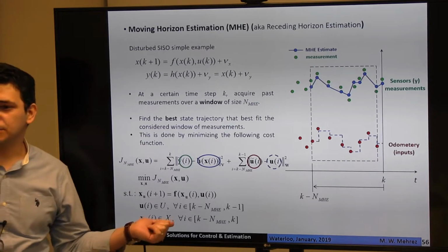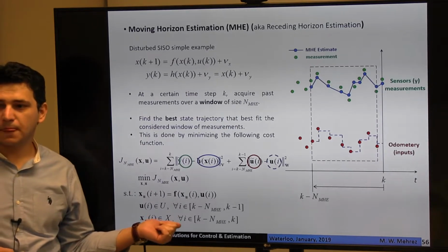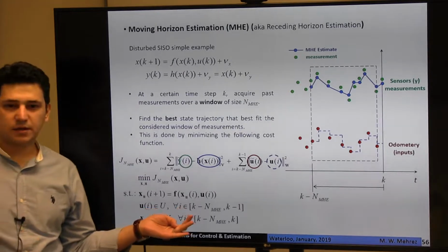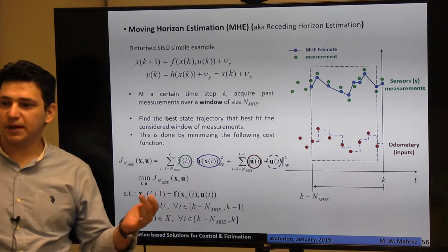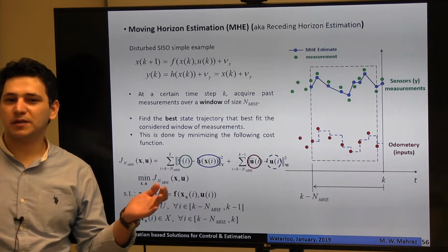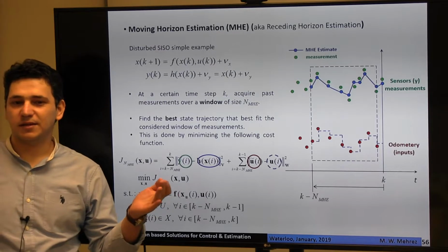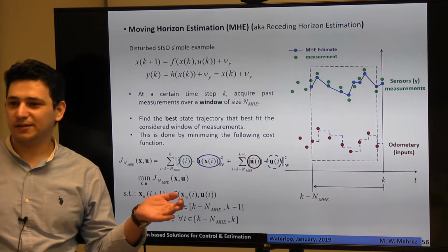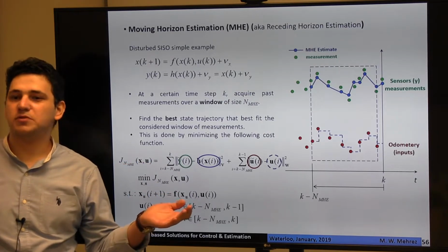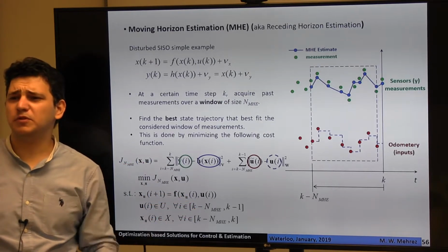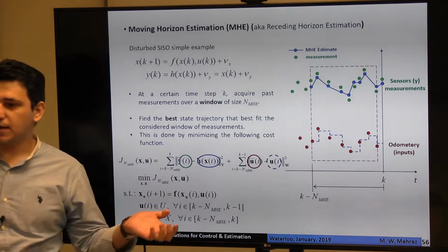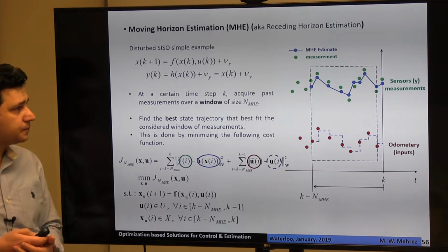Looks very similar to MPC. It's actually the dual problem of MPC. It's like, for linear systems, state feedback and full order observer. The way you calculate K in state feedback, the gain, is very similar to the way you calculate L, right? There you use A and B matrices, and in a full order observer you use A and C matrices. You even use the same Matlab command to calculate the gain K and the observer gain L, right?